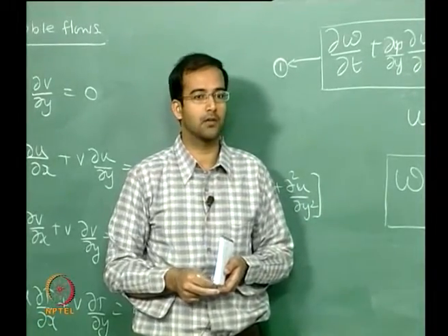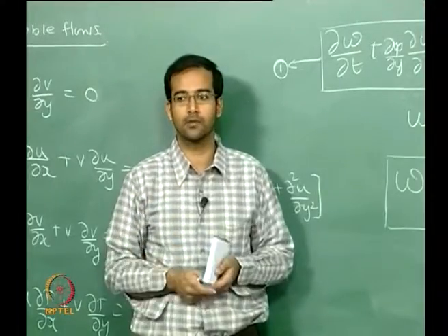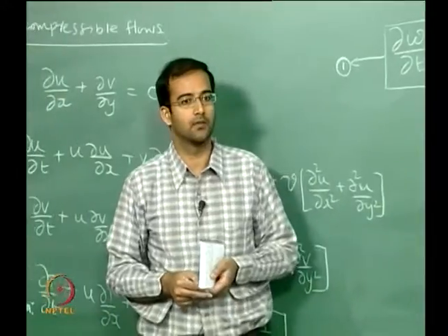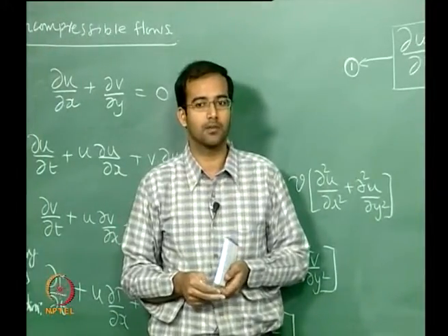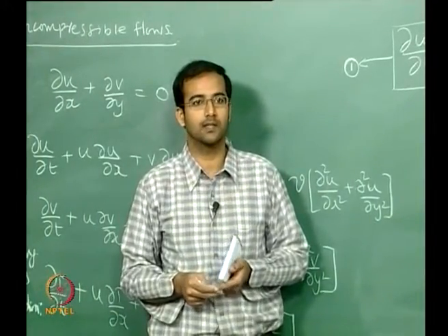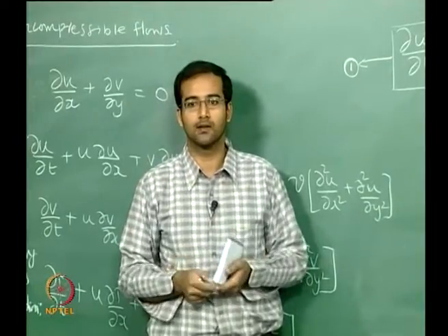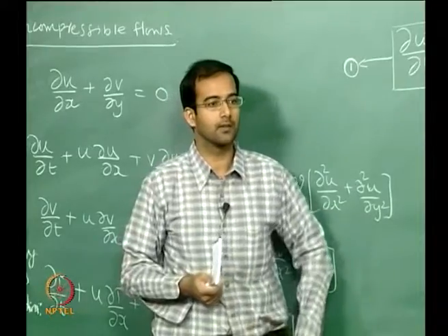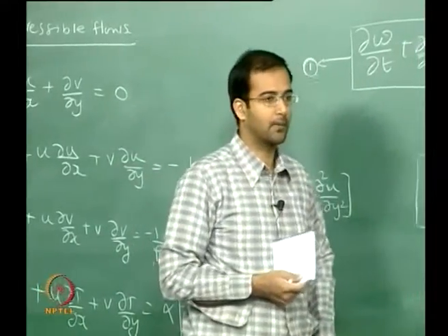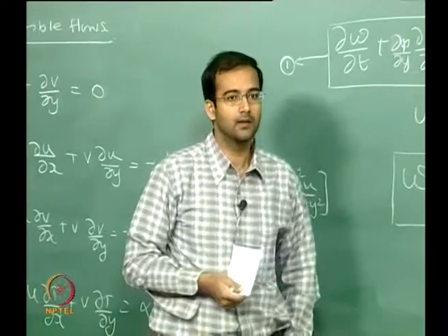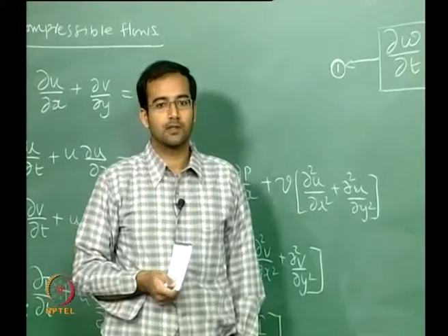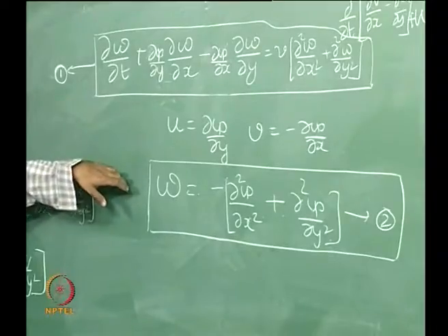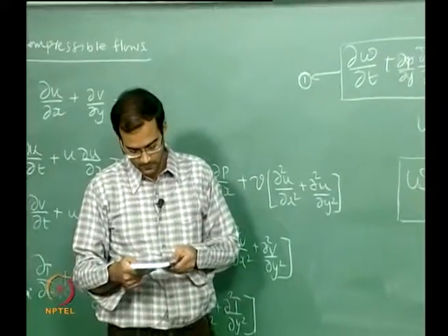So where you have to solve for three equations and you don't have an equation for pressure, that's why it's a very popular technique for numerical solution to two-dimensional incompressible flows, okay. Most of the journal papers that you take for 2D incompressible flows, until recently, where you didn't have powerful computing facility to solve the full Navier-Stokes equations, they were employing the stream function vorticity technique, okay. And this is what you are going to try out also.